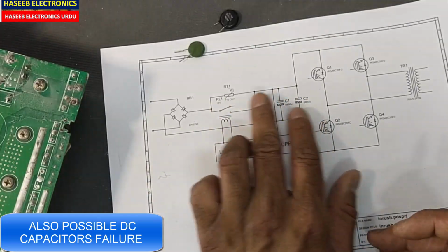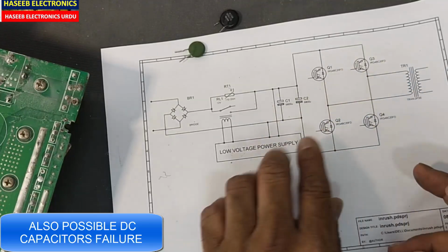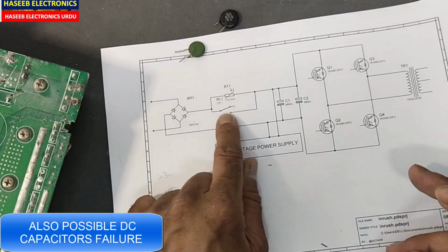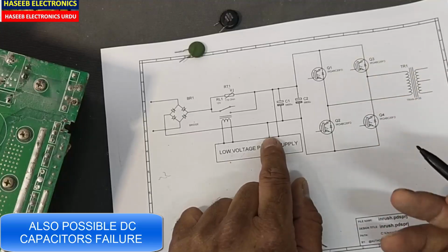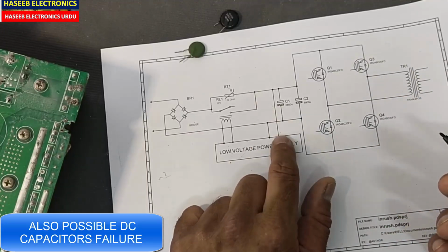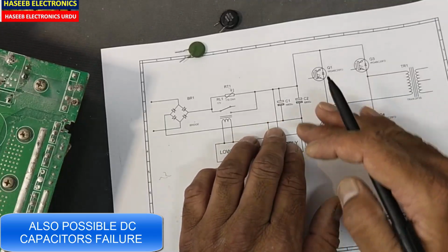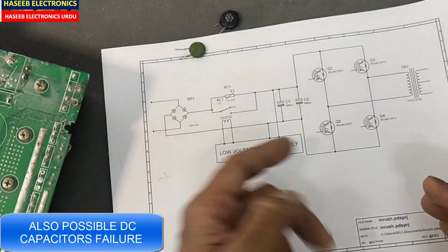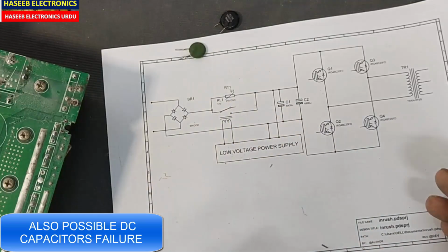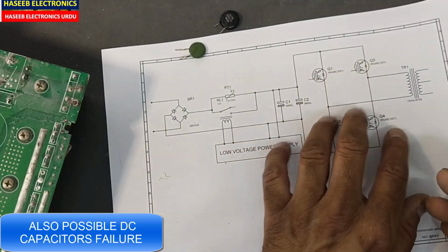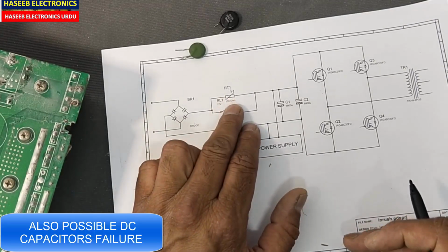because it has its own limits. It will not allow drawing the full current, but the system is drawing more and more current, and the system is not shifting to the bypass. Why? Because this power supply section is not being turned on. When it is not turning on, that means the capacitors are still below the limit. The problem here in the DC rail is the biggest fault in these machines. If the IGBT set or MOSFET set is short circuit, it will blast this PTC most of the time.